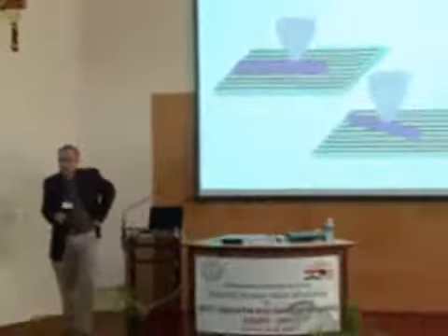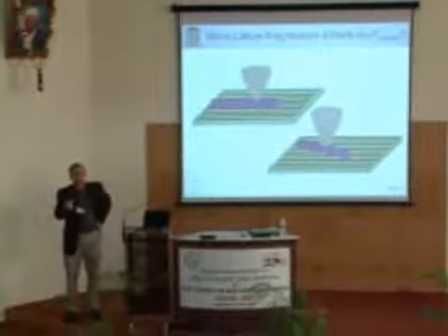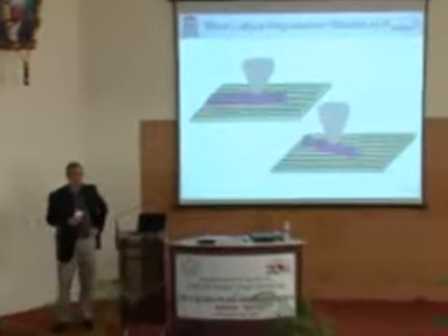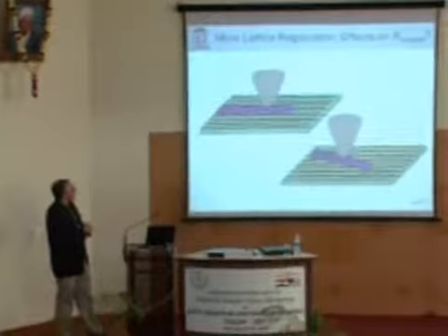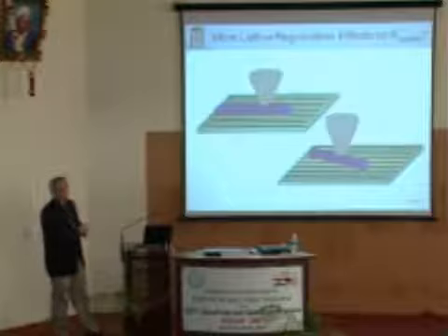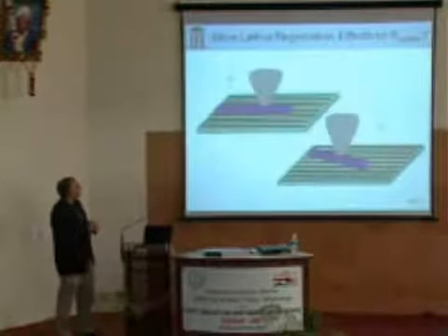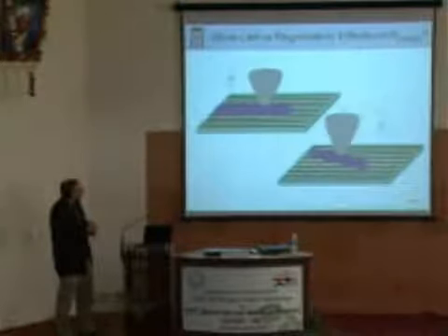The next step for us in our interest in this kind of device is to ask, does this atomic scale interaction reveal itself in the electrical properties of the device? And so for that, we do a simple measurement. Here's the nanotube on the surface. Here's the graphite. We take our AFM tip, and now we attach a wire to it. And that wire is going to carry current into the nanotube, and we collect the current in the substrate. So we're looking at this interface here between the nanotube and the surface.